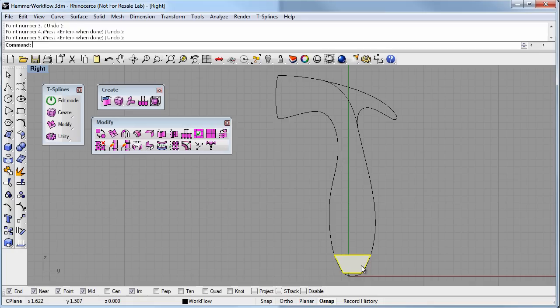To append another face to this face, run the command again. First click the 2 points on the face that you'll be connecting to, and then click the 2 new points of your face and hit enter. We will be repeating this a number of times. One important thing is to always make sure that you are snapping to the points that you want to connect to. It's important to make sure that you have the Rhino point snap on.